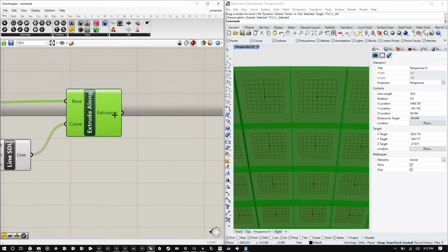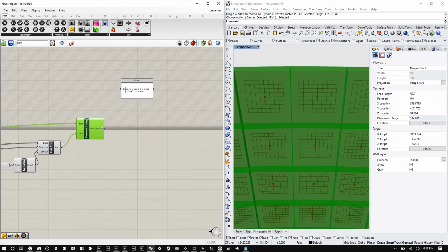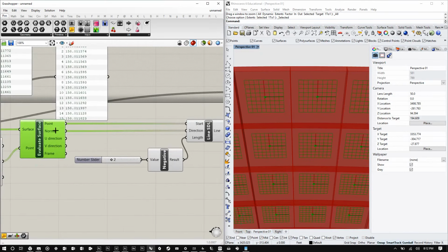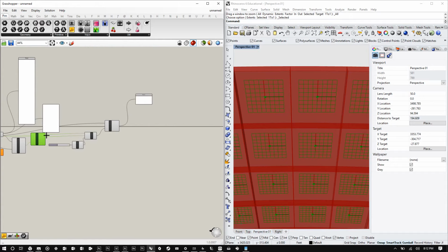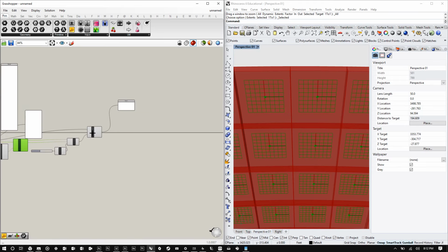So what I'm going to do is I'm going to graft these guys. So each one of them will be treated as their own individual object, operated on by their own parameters. I'm going to use the original point here from the normal, and I'm going to scale them down by 95%, so they'll be slightly smaller than it used to be.